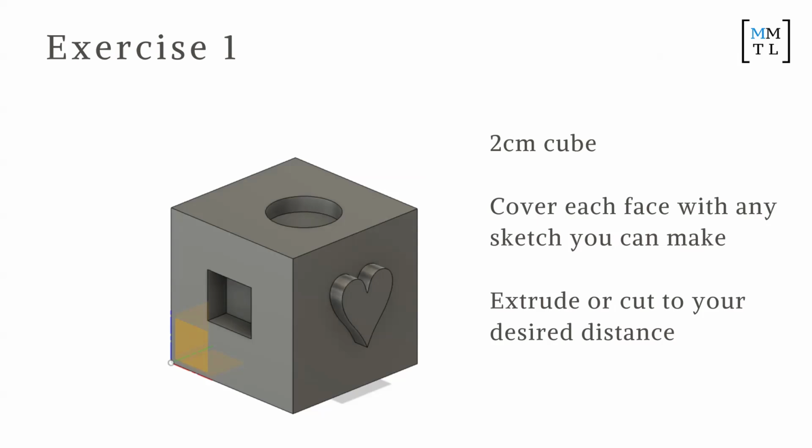Right now you can't see what you're doing because you're in the same plane. When you're parametric, you can just cut through to section. Can you see through the square? Right now you can't see. Oh, yeah, you can. There you go. Nice. So don't stay on the same plane, especially when you're extruding. You want to know exactly what you're doing.